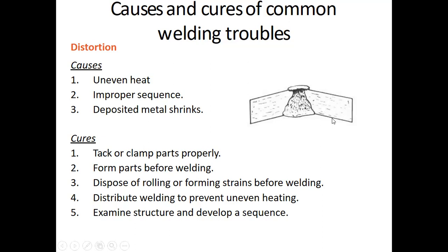Basically, you're trying to roll sheets, right? So that, or any other forming process, will have some strains. Those strains, if they are not relieved, relieved is a proper word to use, if the material does not let go of them, if you do not make it let go through heat treatment or any other process, then that will also cause problems.